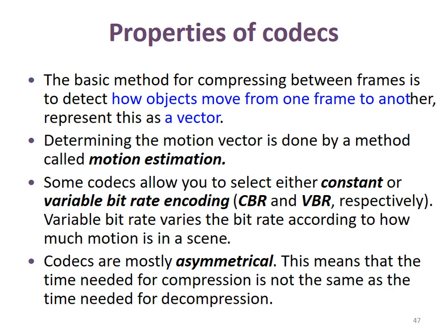Based on the motion vectors, we can see the pedestrian's location in the previous frame, and we can use the content directly from the previous frame. So this achieves the goal of compression. Okay, so motion estimation is very important for video compression because we can use the content that appeared in the previous frames. Next, you will see a lot of algorithms for how to apply different motion estimation algorithms to determine where the objects were in the previous frame.